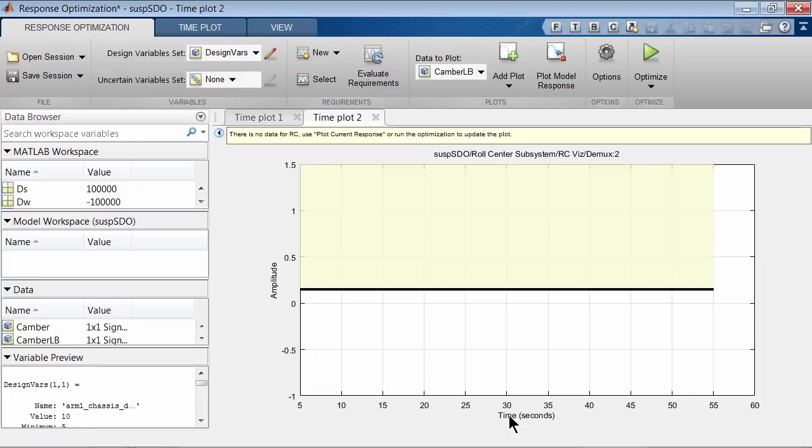Note that we are not specifying a lower bound for the roll center criteria. This is by choice. The rationale is that we would like to know the lowest roll center position possible for our current configuration. In reality, we might need a lower bound for the roll center as well, so that the optimized roll center is not so low that the chassis might actually hit the ground. Sometimes it's a good idea to optimize for lesser parameters with less stringent bounds to see how the algorithm performs.